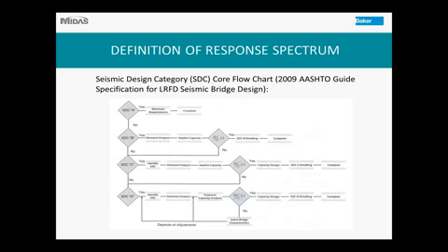And based on the seismic design category, the code asks you for a different flow chart. As you can see, for seismic design category A, which is very light, basically no seismic hazard area, you don't need to do anything. Just follow the minimum requirements and you'll be done. For seismic design category B, you need to do a demand calculation. You don't have to identify your earthquake resisting system. You can calculate your displacement capacity per the implicit capacity equations and check whether the demand over capacity ratio is less than 1 and be done.